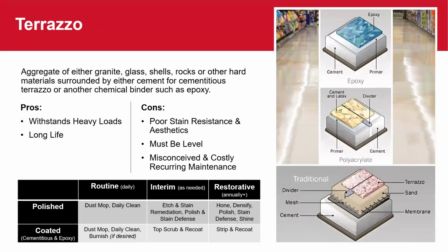The next substrate that you find out there that is cementitious would be terrazzo. Most of the old, or all of the old, terrazzo that is out there has a Portland cement base. So you take Portland cement and then you add marble chips to it, and that was the traditional terrazzo. Today, we've got epoxy terrazzo, polyacrylic terrazzo, and there's a lot of terrazzo that is not cementitious out there. How you take care of that floor is different if it's cementitious or if it's not.